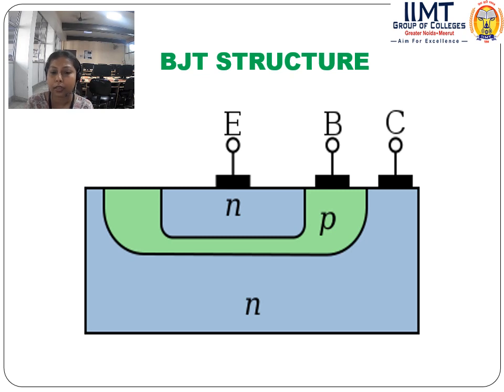According to that, we can see that we have to apply the lithography technique for the BJT structure three times, because after the substrate, we have to select the portion for the P-type layer, and after development of the P-type layer, we have to select the portion for the N-type layer. That selection process is mainly done by the lithography technique.